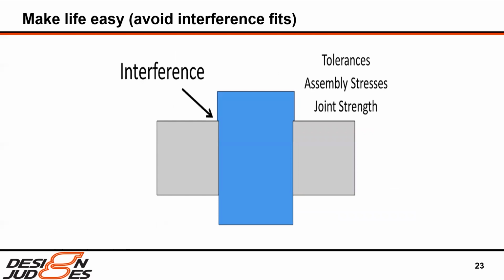Another thing that I would typically advise avoiding are interference fits. They require careful design and tight tolerances. They're really hard to disassemble, and you'll need to give a lot of consideration to the tolerancing of the parts, and the resulting range in the potential stresses and joint strengths from the range of tolerances, right? So there's definitely applications where interference fits are good, but it requires a lot of design to do them right.